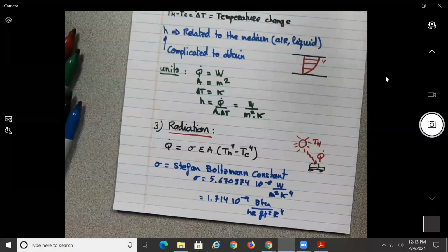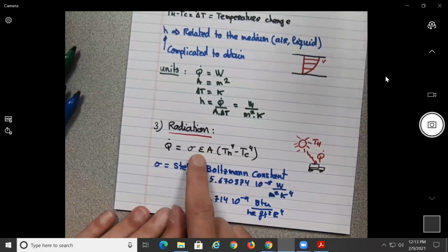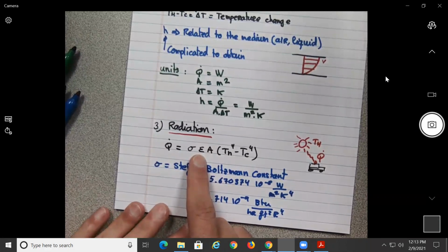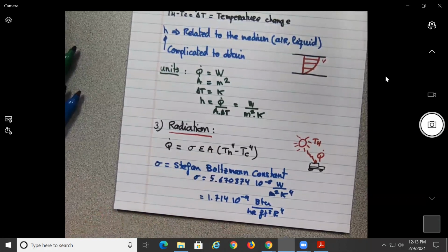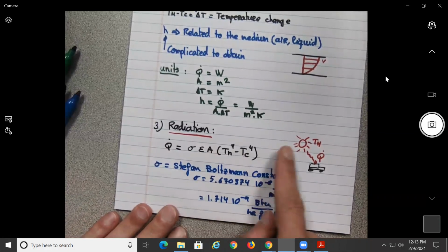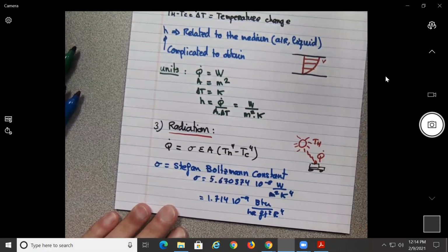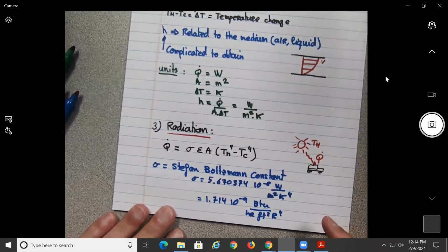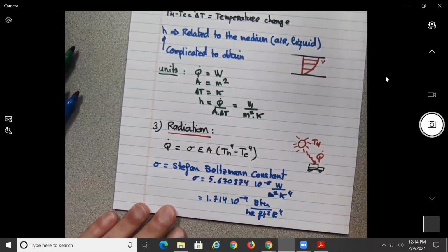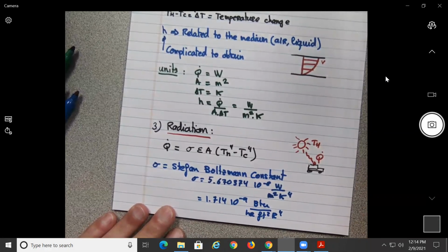So that factor is taken into consideration by the epsilon, which is interesting because it's called the emissivity, but it could also be called the absorptivity, no? It's not how you absorb. The real equation really should be Q absorbed minus Q emitted, okay, for the emissivity. But since those values are so close to each other, somebody had to decide between one and the other to write down the equation. So they just decided to use the emissivity.